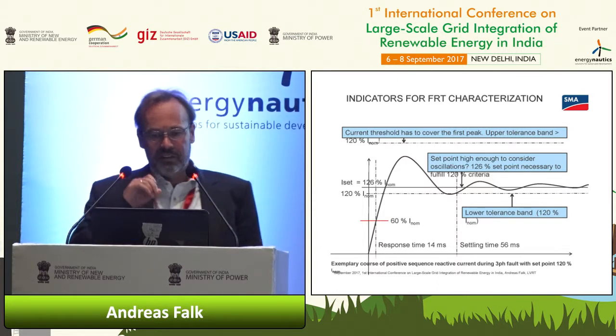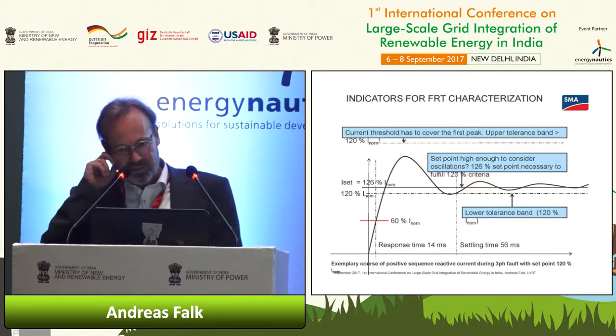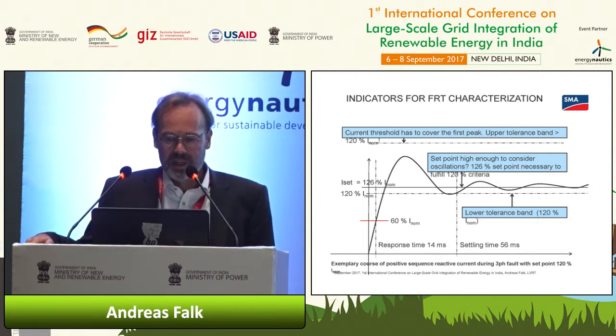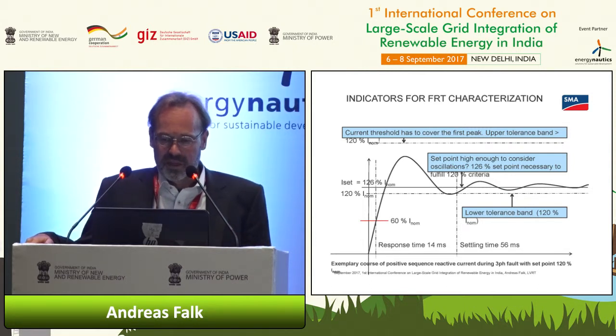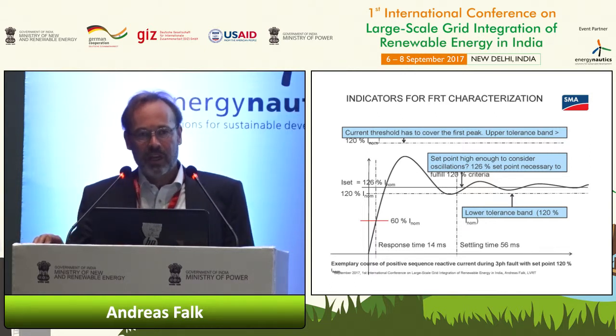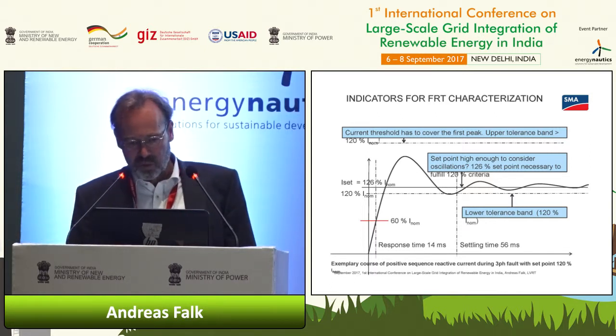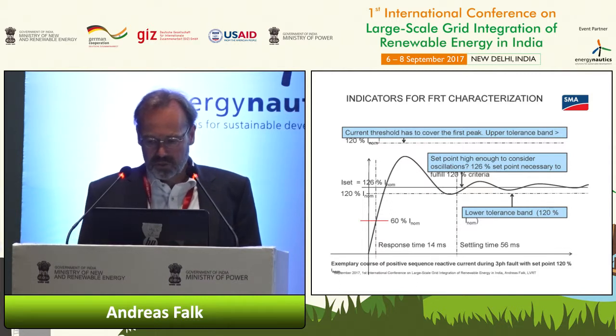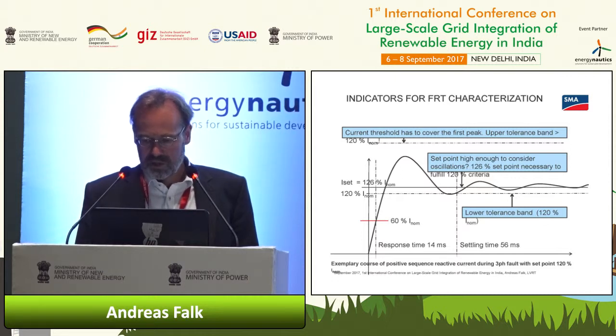And in that case, the settling time is required to be 60 milliseconds, so it has to be tuned in a way that we are sure to reach the 120% within 60 milliseconds, and therefore we have to increase the set point from 120 to 126% to be sure to reach the 120% after 60 milliseconds.